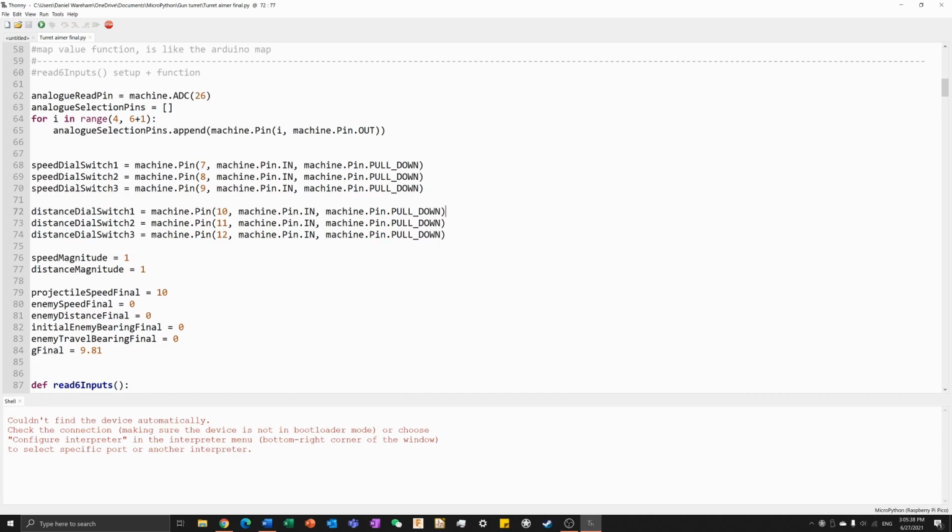This array is containing the 3 pin objects, which are the 3 pins required to set the binary value to the 74HC4051 chip for it to select the correct input to give back. And it's easier to set it in the form of an array rather than having to individually set the value of all 3 pins every time it needs to be done.